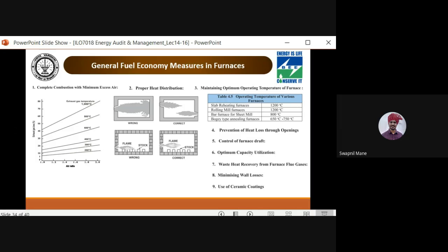Okay. Now, what is the best method of loading? The best method of loading is trial noting. So trial noting of the weight of the material put in at each charge. For each batch you measure the weight being put in, or how much time it takes for the temperature, or how much fuel is being used. All these things taken into consideration, you will get the optimum value of the material to be loaded inside the furnace. Okay.